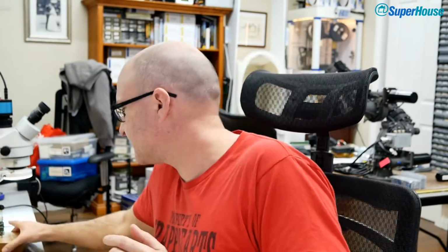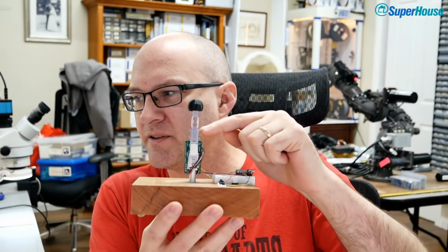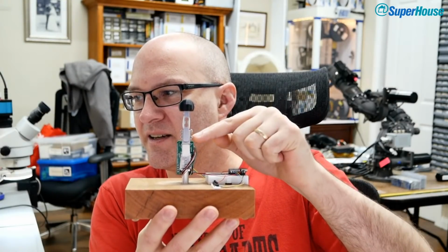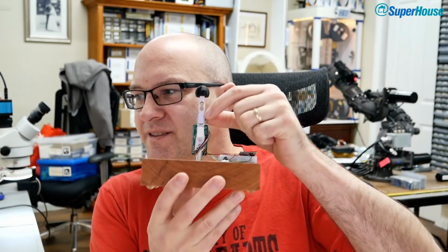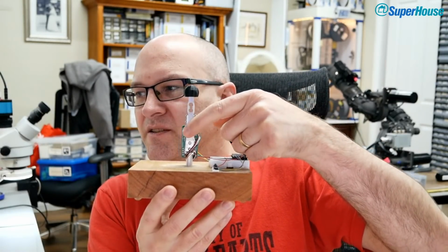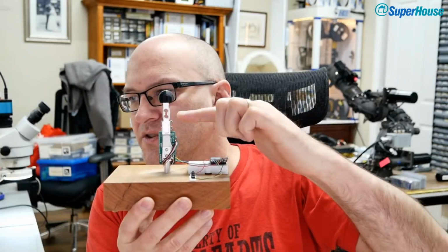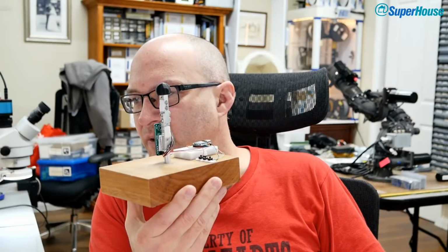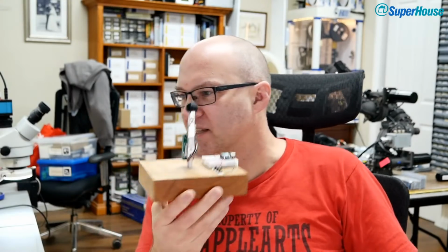But yes, we have actually done a few things. It's a little bit hard to see, but the end of one load cell is actually going inside the other load cell. This one has been machined with a slot, and you can see the bolts that go through. It's been machined to look like a Y shape, and then the top load cell slides down into it, and it's cross drilled so that the bolts go through. Part of the reason for that was to make it mechanically very rigid, but it also reduces the length by merging the two load cells together.